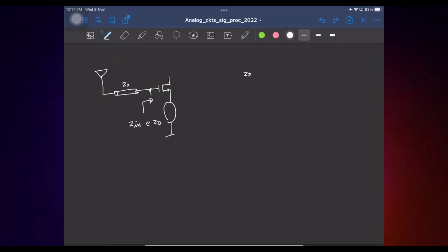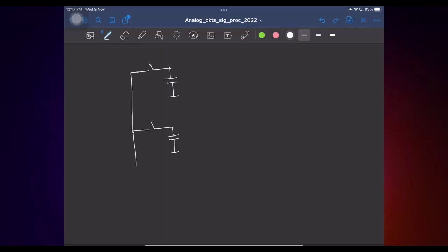And in this course, of course, we saw that the recent trend is to have LPTV based circuits as the RF front end, right? So this, of course, is a passive mixer. And of course, we saw that in practice we'll have in-phase and quadrature components. So we'll have a double balanced IQ mixer like this.